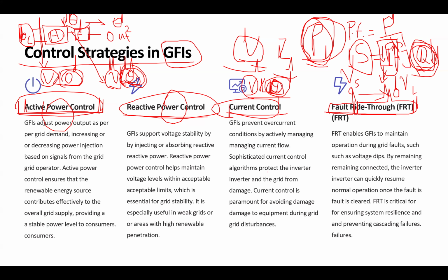If you wanted to follow that chaotic fault situation at your terminal, basically it means you have to inject a tons of amount of current. And because it's a chaotic system, your inverters become unstable. What normally happens is the inverters are forced to cease power, so they're forced to cut themselves out of the system, and if that happens, it basically means there is going to be a cascading failure of your inverter power